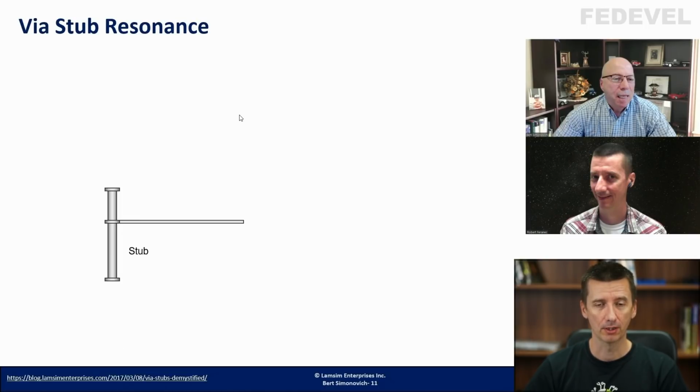So on this picture, you can see a through hole via, which is starting, for example, on the top layer, ending on the bottom layer. And the signal is routed from the top layer, and it continues somewhere in the middle of the PCB. So basically, this part of the via is not used, and you will see why this is a problem, or when this can be a problem, and what it can do. So let's start my call with Bert.